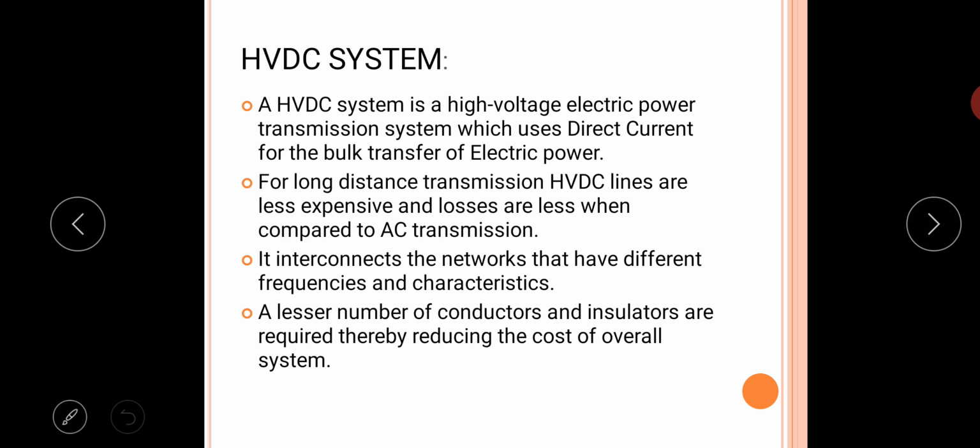Normally, an HVDC system is used to transmit power between longer distances since we require a rectifier and the inverter unit at the sending end and the receiving end, which becomes expensive for shorter distances. Generally, it can be installed for a distance of 500 km or more. An HVDC system has an advantage that it can interconnect systems operating at different frequencies.